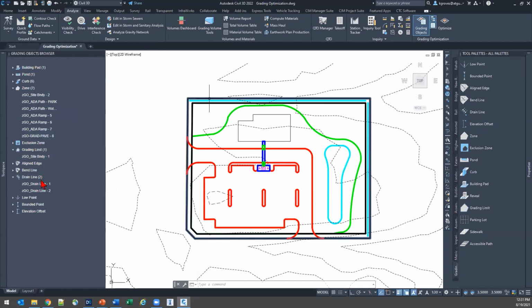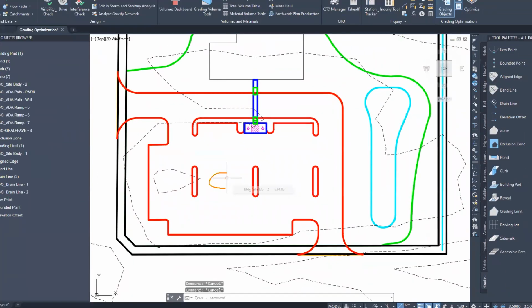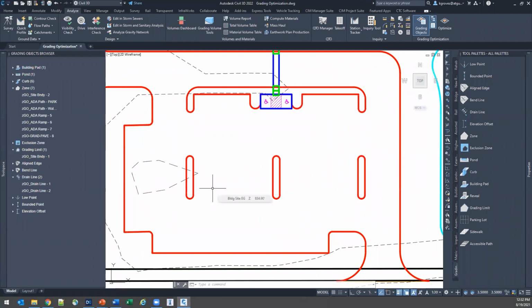building, some drain lines. Oh, I want more drain lines. So I want this area to be a low point, and I want this area to be a low point, and my stormwater might look a little bit like this with catch basins and then draining out into that basin. We need to add those drain lines. We do also need to remember, first click is the high point, second click is the low point. I'm just going to give myself a little circle centered between the center.